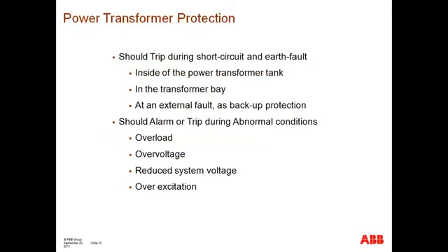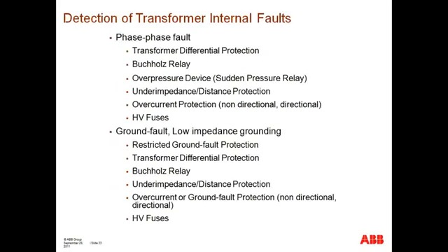So what are some of the requirements for power transformer protection? Well, it should trip during short circuits and ground faults inside of the power transformer tank, I'm sorry. And in some cases, depending on the scheme, it's also important to trip at external faults to provide fast backup protection. Again, we're discussing multifunctional microprocessor relays, which most of the ones available in the market have this capability.